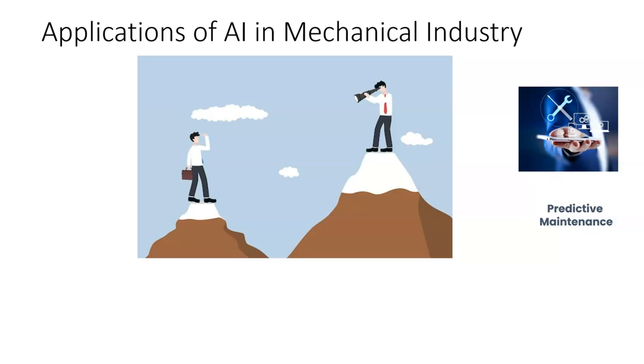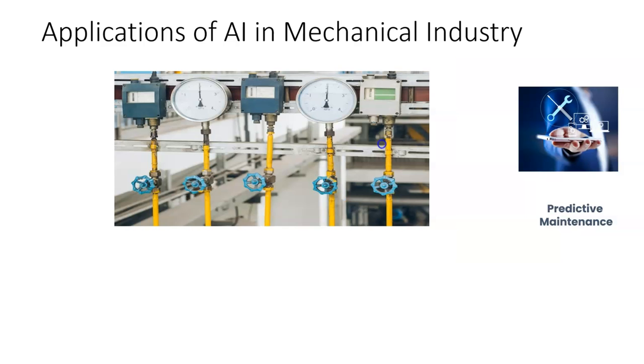If you are using AI-based systems, you can move from preventive maintenance. In preventive maintenance, you can't predict future failures, right? If you're trying to predict future failures, it's only guesswork. Whereas when you are using predictive maintenance based approaches, you are actually predicting failures. How are you doing that? You are doing that based on multiple metrics. Let's say you're talking of a complex system that manufactures cars. You can measure the pressure, vibration, speed, temperature of those equipment. You can monitor these parameters in multiple dimensions. You can study the interaction effects.